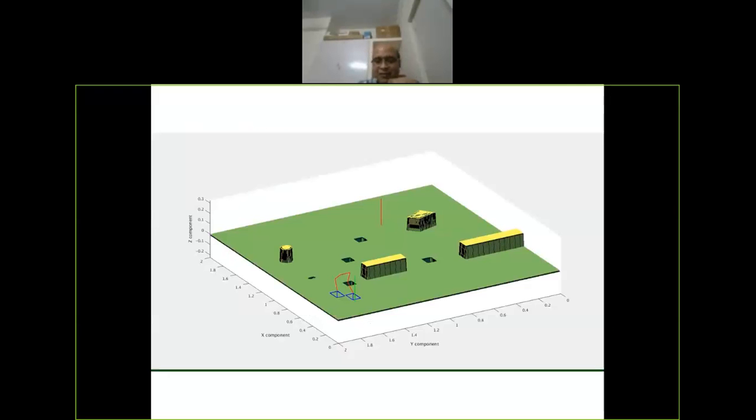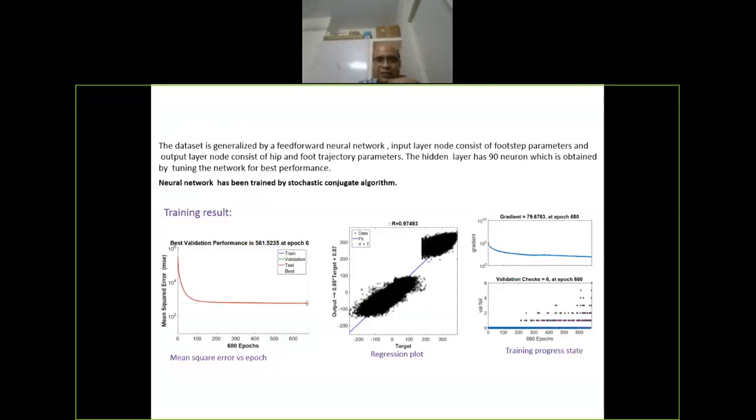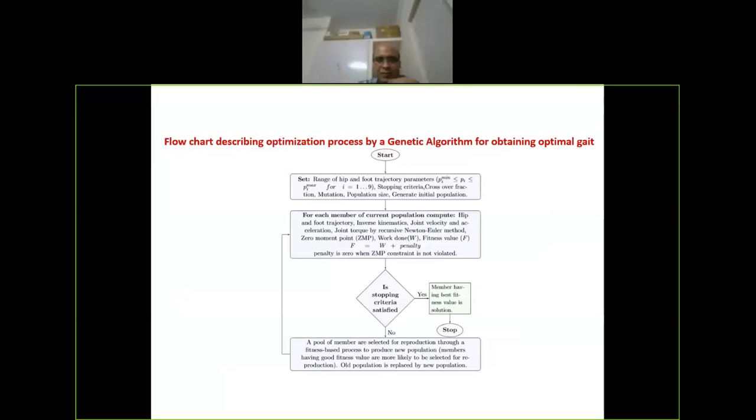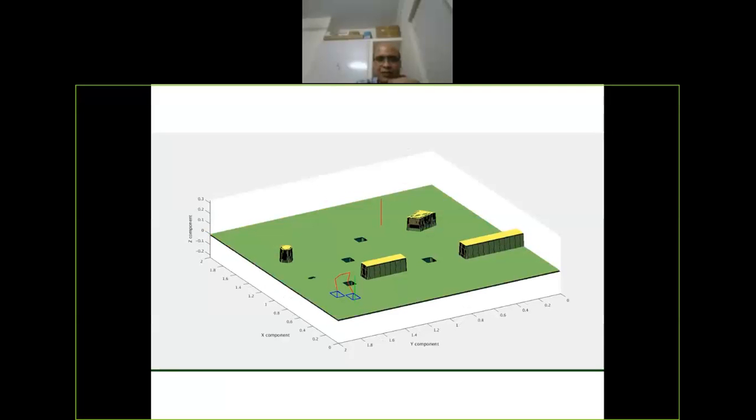Okay. Now here, if you're going from one point to another point, let me come here. From here I'm going there, you can go in infinite ways. These would be the paths by which it can go, which is basically called path planning. How to find the path to take you from one point to another point without hitting an obstacle, without getting into a ditch. But when you're following the path, you have to give joint angle commands at the joints, okay? Which means control will be at the joint level now to take the system from here to there to follow the path. That is what we call motion planning.